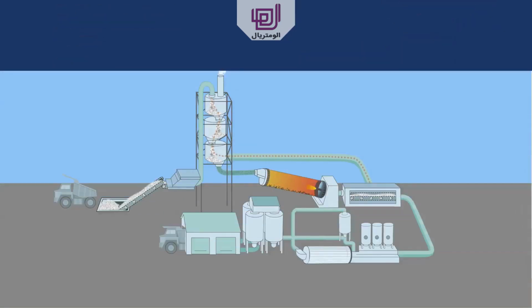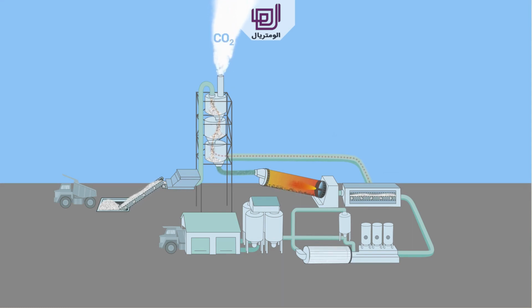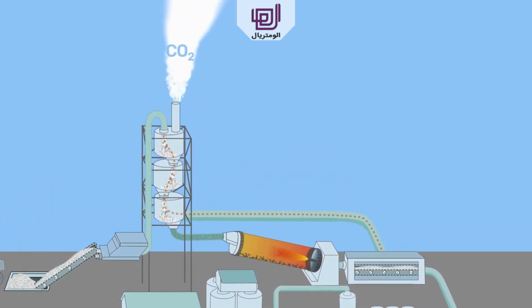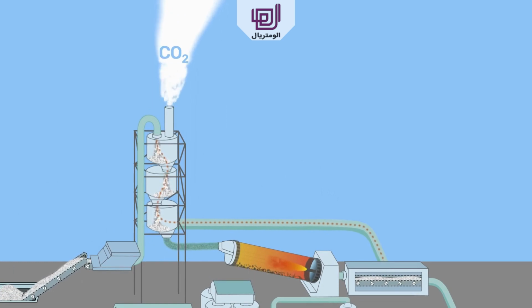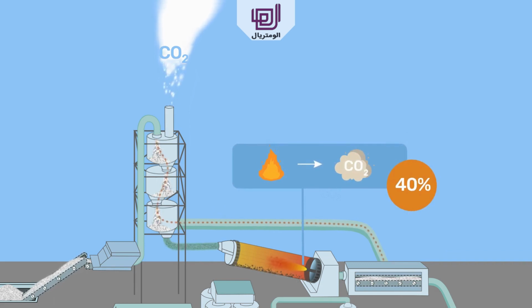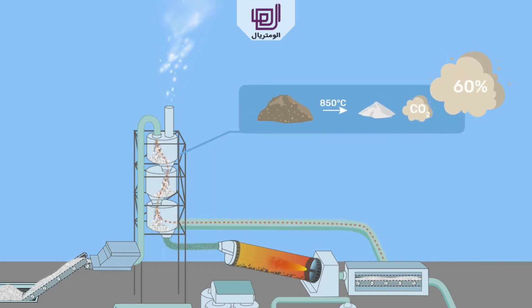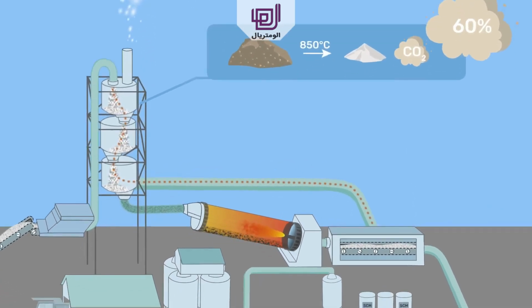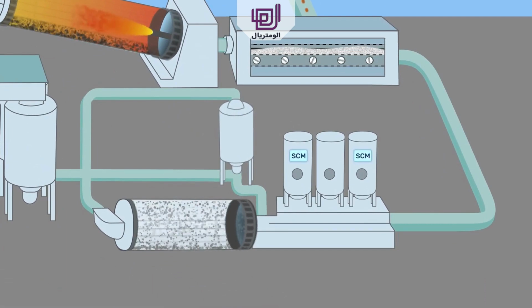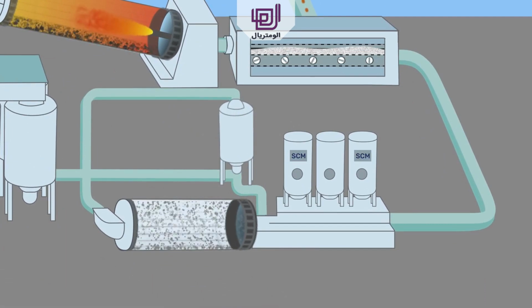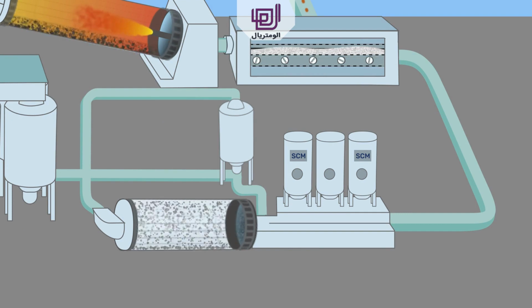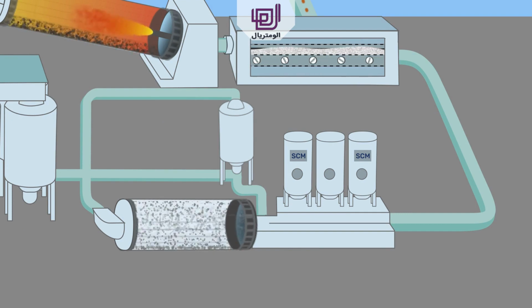In conclusion, the manufacturing of Portland cement is a highly optimized and well-controlled process, of which the main challenge today consists in reducing the associated CO2 emissions. Even if we completely move to renewable energy sources, this would only address 40% of the problem. The remaining 60% emissions are related to the calcining of the limestone and may be reduced by substituting part of the clinker by supplementary cementitious materials, referred to as SCMs. These are added during or after the grinding, as discussed in a separate video.